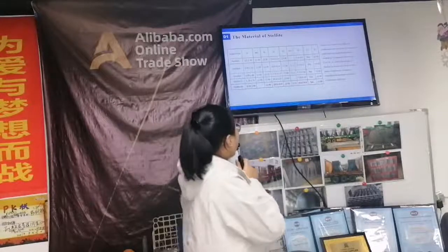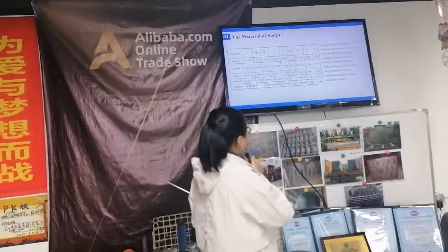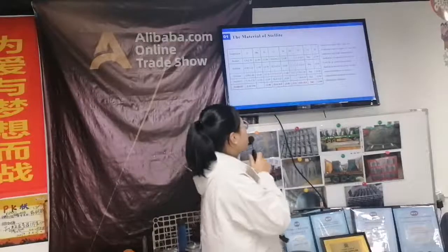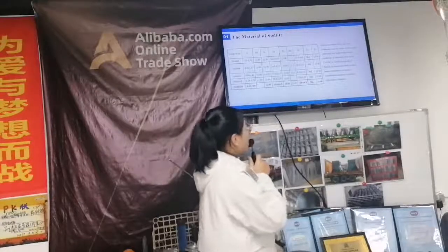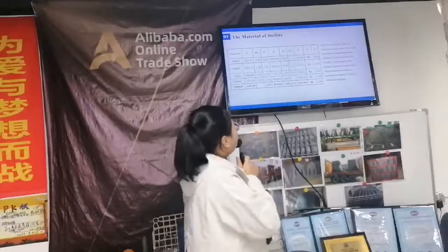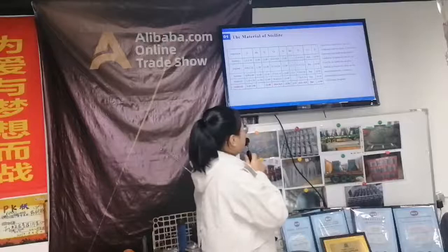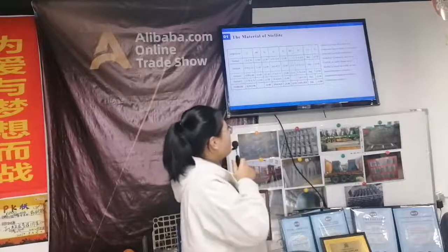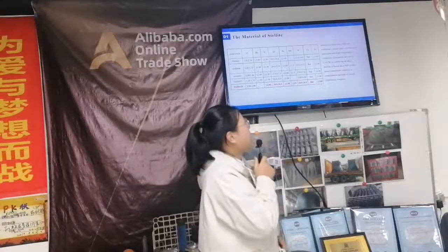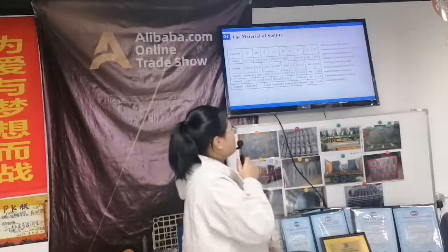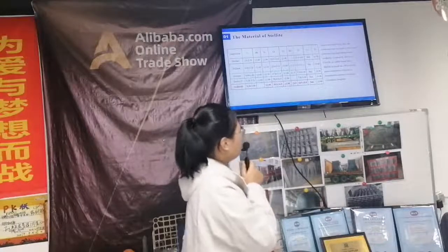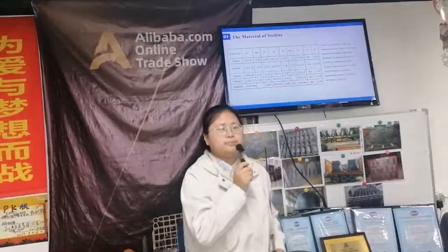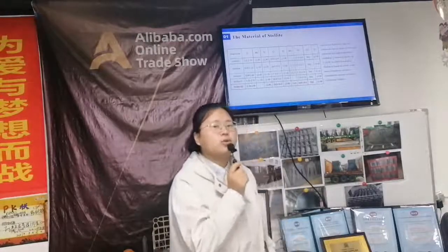Stellite 4. For carbon is 0.8 to 1.2%. For manganese is less than 1.0%. For silicon is less than 1.5%. For chromium is 28 to 32%. For nickel is less than 3.0%. For tungsten is 12.5 to 15.5%. For iron is less than 3.0%, and the cobalt is balanced.